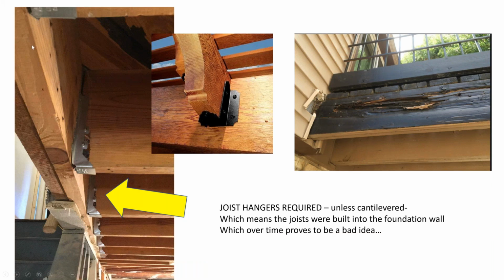Joist hangers are going to come up in your inspection report often as well. These are examples of joist hangers. They are going to help offset the load and secure your deck from falling. They do fall. We have had people that have had too many people on their deck, and if they just have nailed this together, they're going to come loose and the deck's going to cave. So joist hangers are a very cheap fix. You can do it yourself. It's not hard, but look for them when you're showing a property.